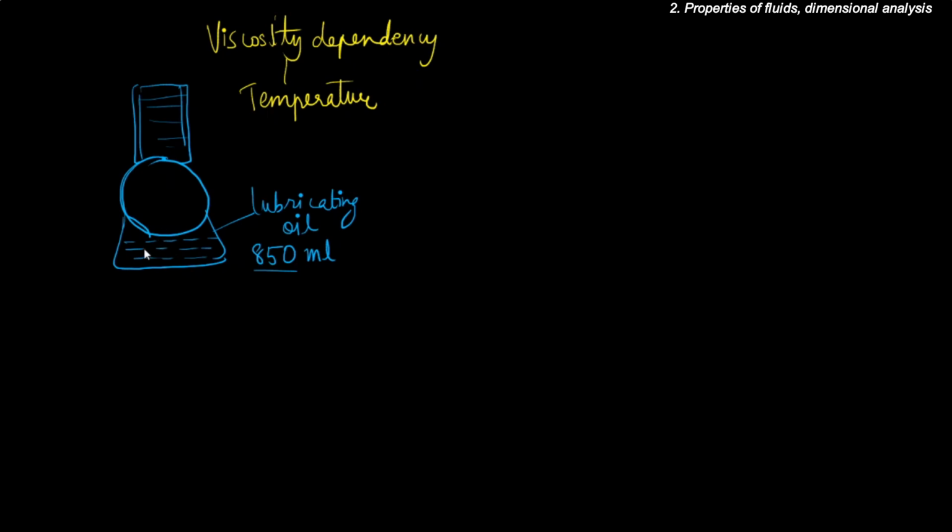Now, the engine runs at high temperatures and splashes oil from the crankcase to the walls of the piston. As the temperature increases, the viscosity lowers to such a point that it allows for smooth operation. It is engineered in such a way that the lowering of viscosity is appropriate for the operation of the bike.